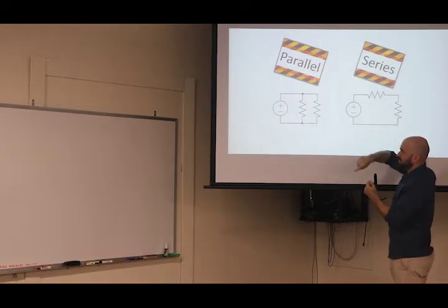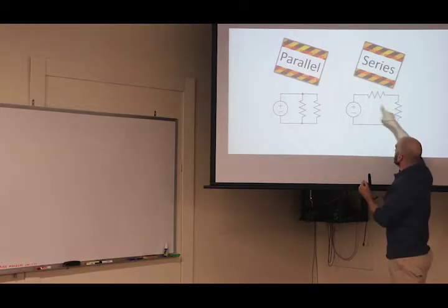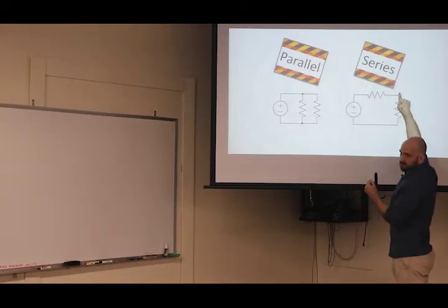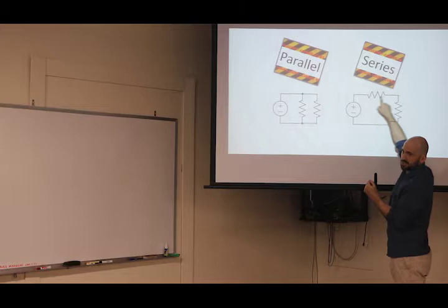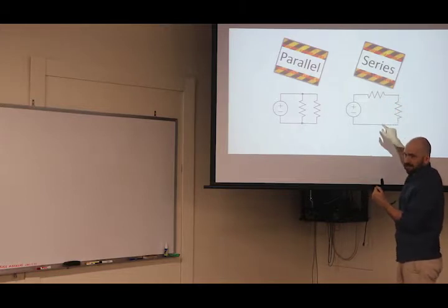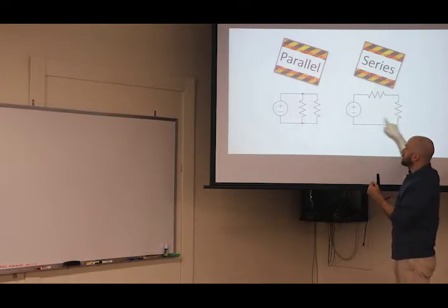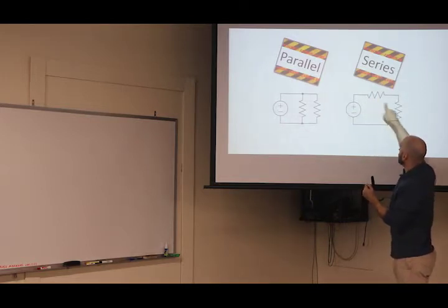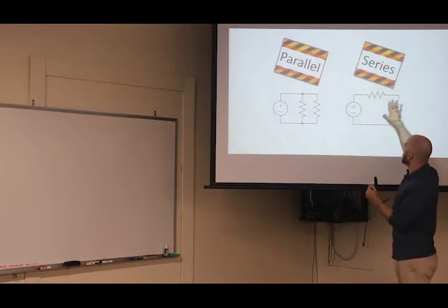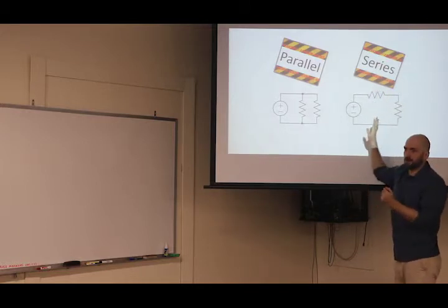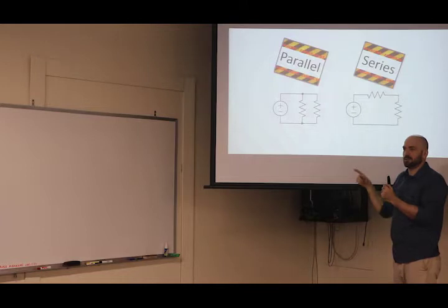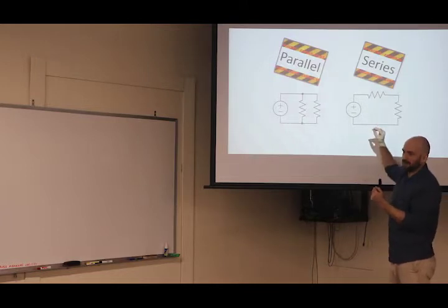Well, I'll explain why in a moment. These are the same resistance. So here it's going to be 4.5 volts, because half the resistance is here and half is there. And the part that I was sitting on the fence about explaining is that you're actually adding the resistance together. So it's 9, and then 1 plus 1 is 2. That's 2 ohms. You can figure the current then. 9 divided by 2, 4.5 amps.